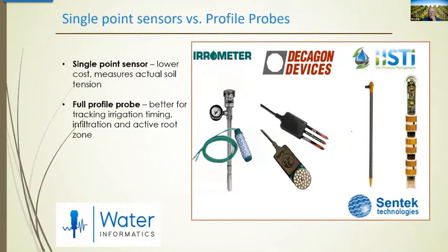So these are different soil types. You can see, these are the classic ones. You see aerometers. The one's a gyprock, that has the coiled wire. You see the other one, John, that's a tensiometer. Yeah, that's a tensiometer. You can see the gauge there. What you do is, that's a liquid filled. It shows tension in a plant, and that is a critical measurement. The problem with that sensor there is that it measures one spot in the profile, right?